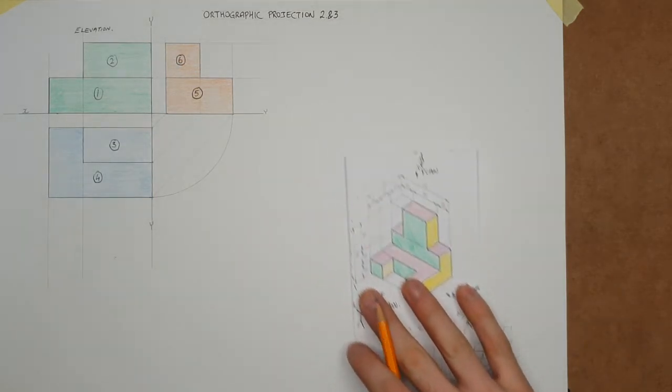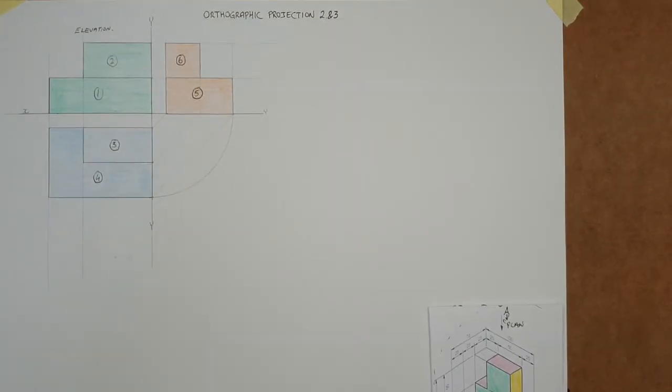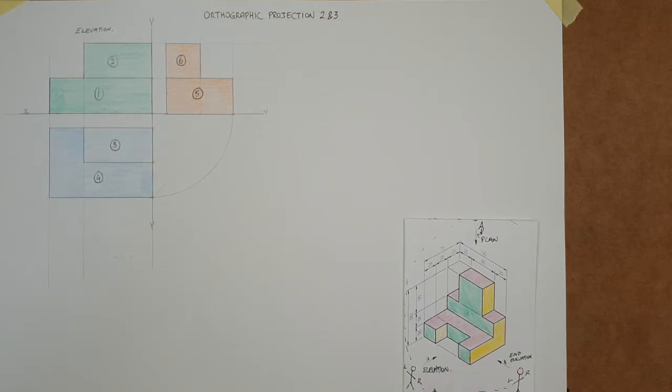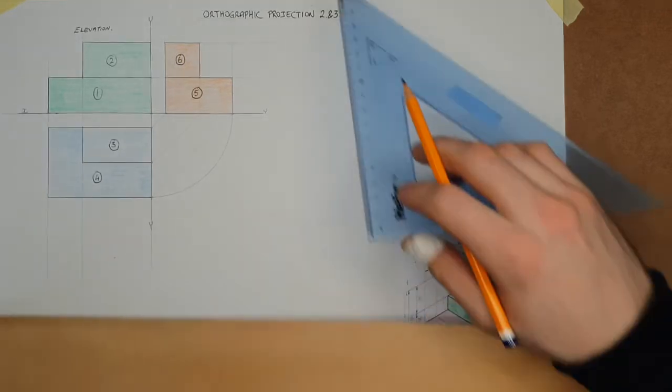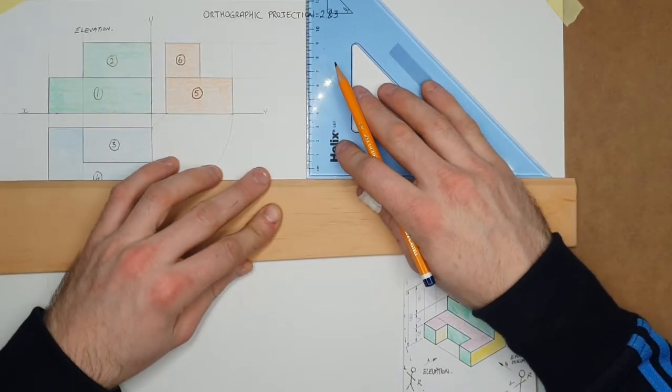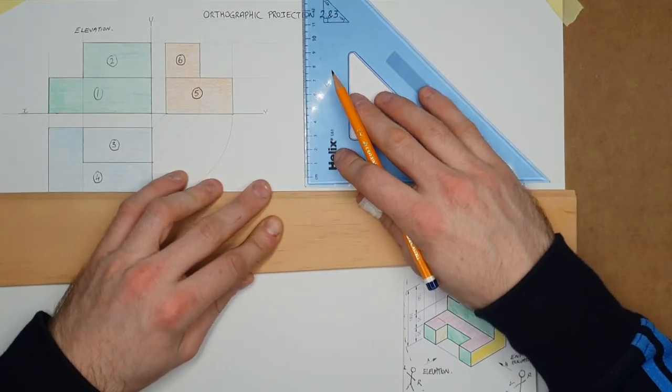With that in mind, let's go ahead and start drawing. We're going to start off now with the view A. So just what we can see in green, everything again is multiples of 25 in this question, so it's nice and handy for working with. The overall height of the object is 100, so just to ensure that this fits on the page, I'm going to come down 130 from the top of the page.